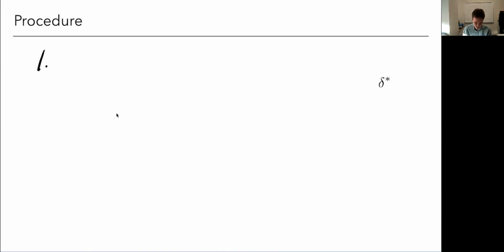Okay, so now number 3, we're going to do the inviscid solution with the normal velocity not equal to 0 this time. Right, we're going to use this new modified boundary condition. And then we may need to go back and repeat again. Okay, or in a better way, we don't have to do this fixed point iteration. We could couple these. We could solve the residuals in the same way, like a Newton method or something. And that's typically what a panel code does that has an integrated boundary layer method with it, a viscous solution with it.